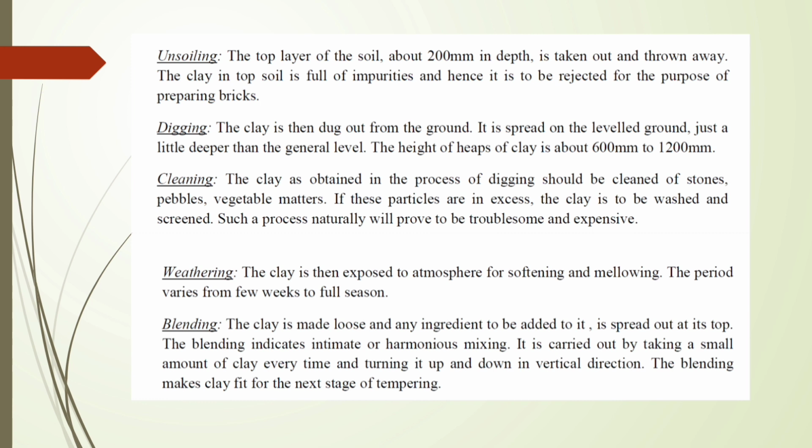Unsoiling. The top layer of the soil, about 200 mm in depth, is taken out and thrown away. The clay in top soil is full of impurities and hence it is to be rejected for the purpose of preparing bricks.